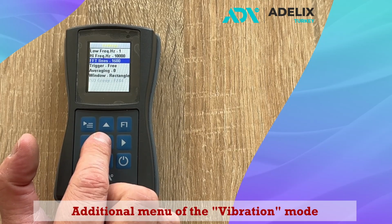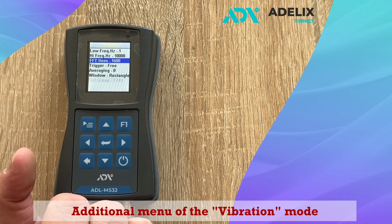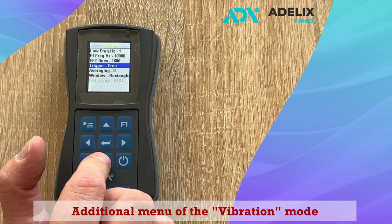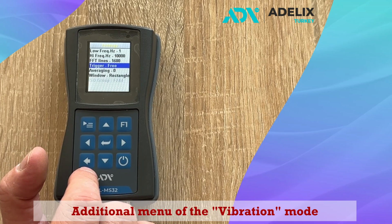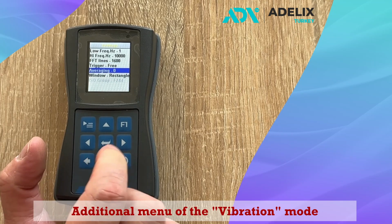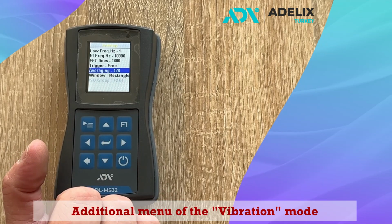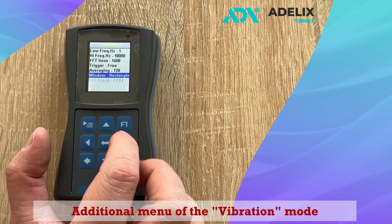Select the number of lines in the spectrum from 400 to 1600. Choose between a free trigger or a carrier frequency trigger. Set the number of averages from 1 to 128. And also modify the display mode.